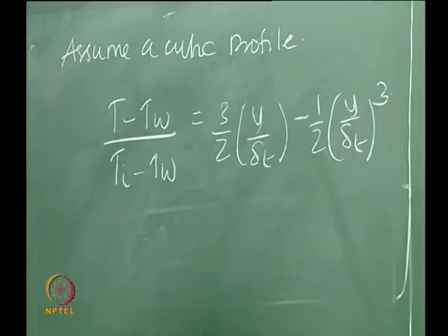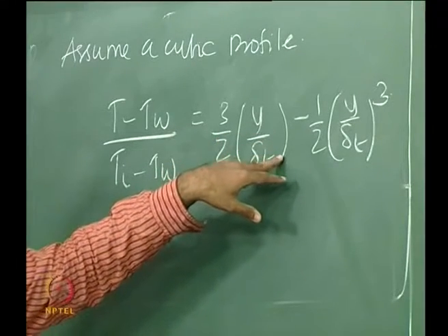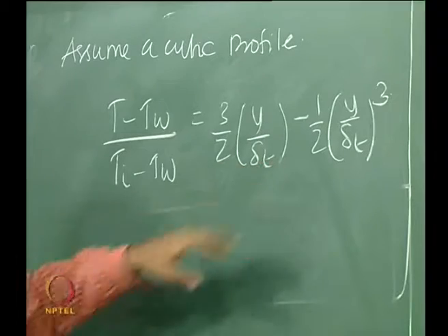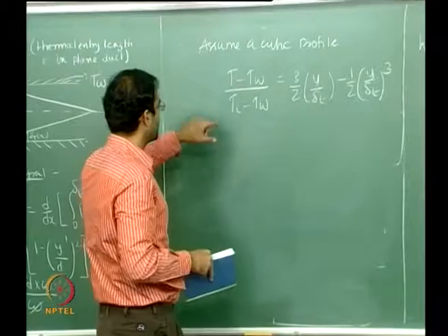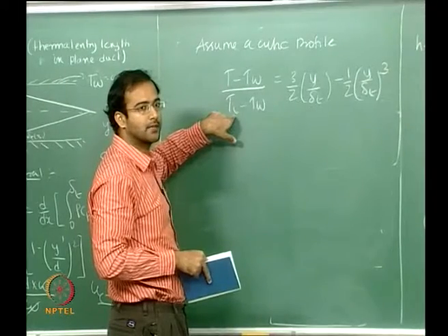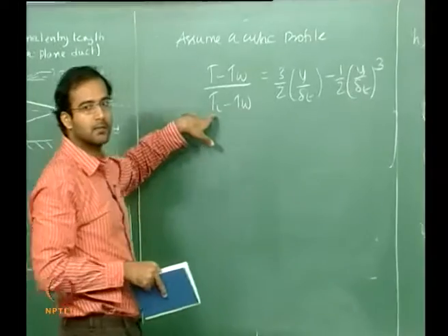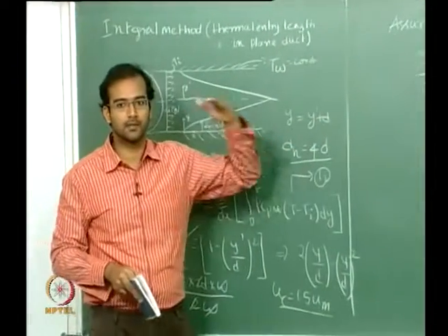Okay, so if you recollect, this is the exact cubic profile that you got for external flows. The same profile, only the non-dimensionalization is a little bit different. You have T minus T wall by Ti instead of T infinity minus T wall. Here your free stream temperature is replaced by your inlet temperature at the edge of the boundary layer.